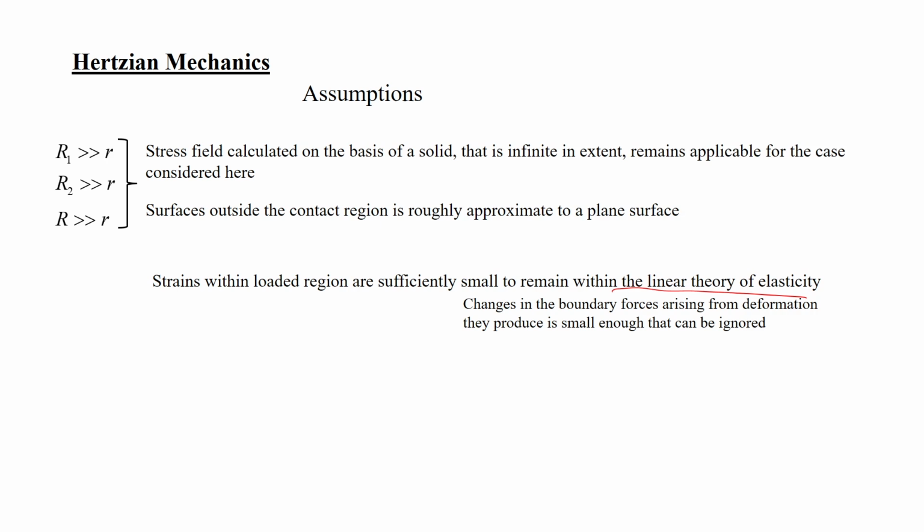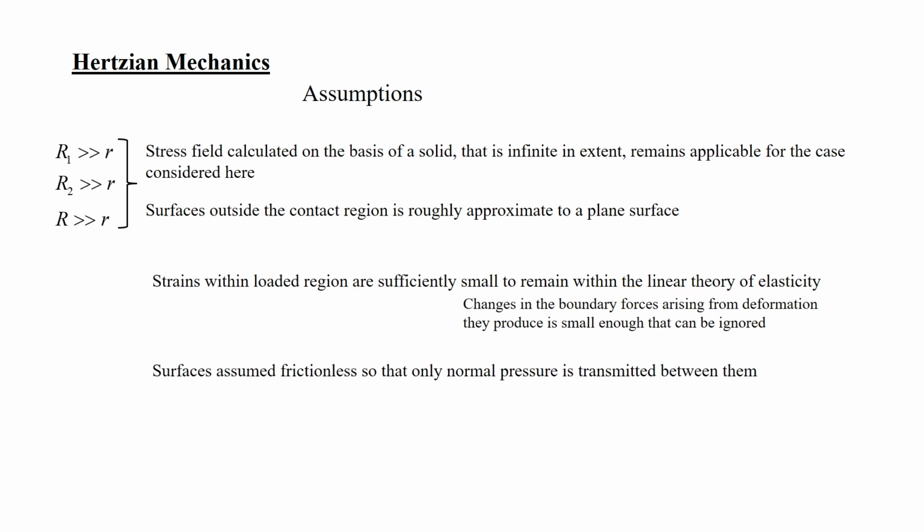Now, these are consequences of this. Another consequence of this assumption is that the changes in the boundary forces arising from deformation are negligible. That means that when you apply the load, there is deformation happening, but this deformation is small enough that it does not change anything, like the stress field outside or inside. It is in a linear regime, not in a non-linear regime. So, it is quite small, that is important. And then it is assumed frictionless, so that only normal pressure is transmitted between them.